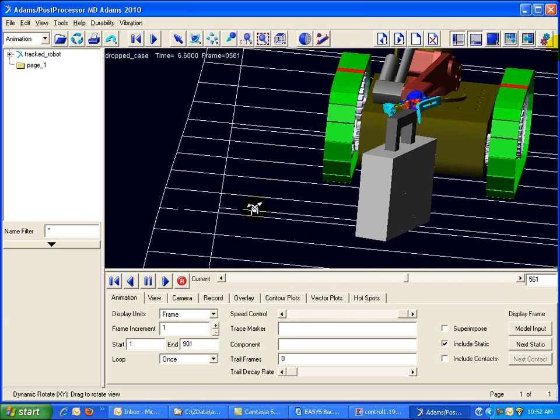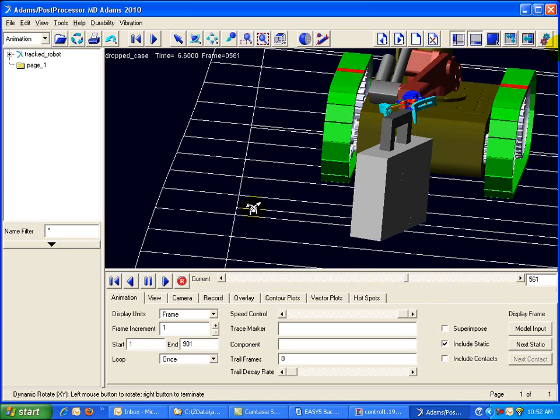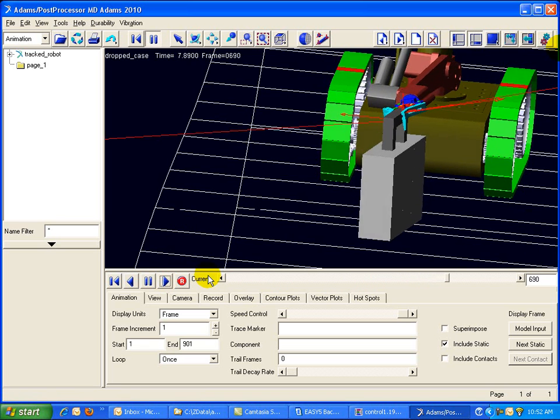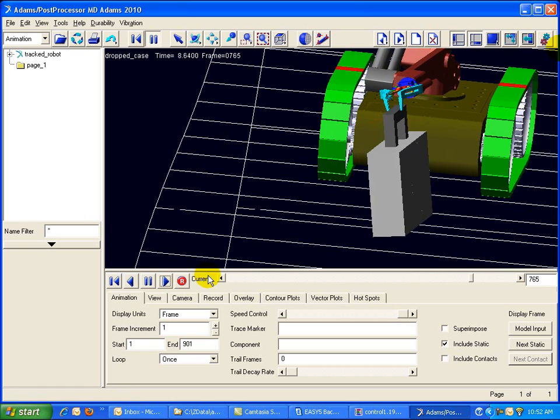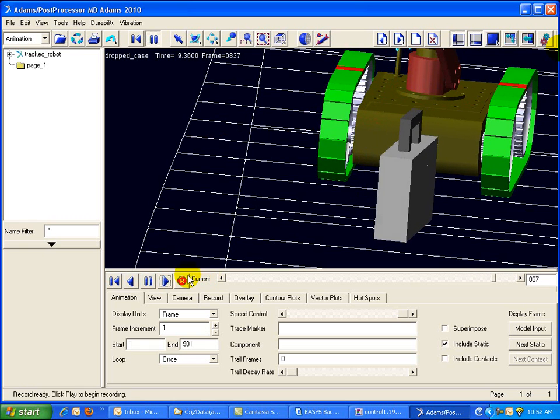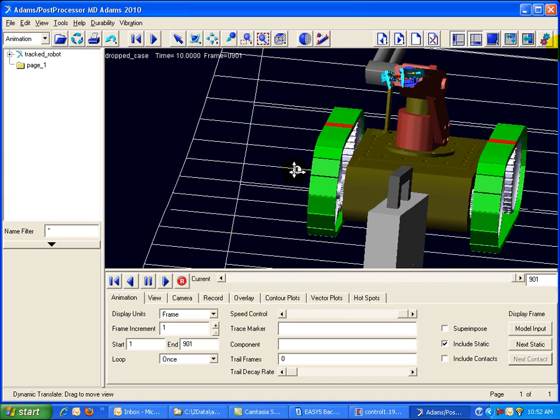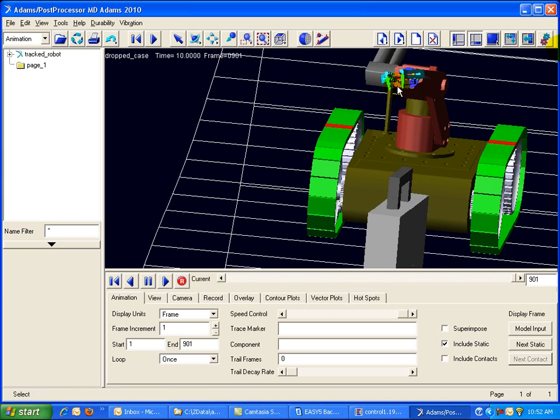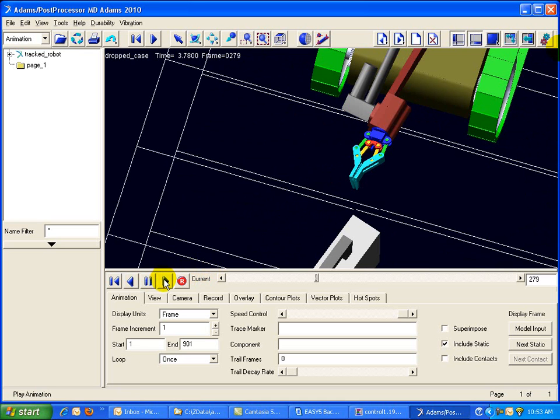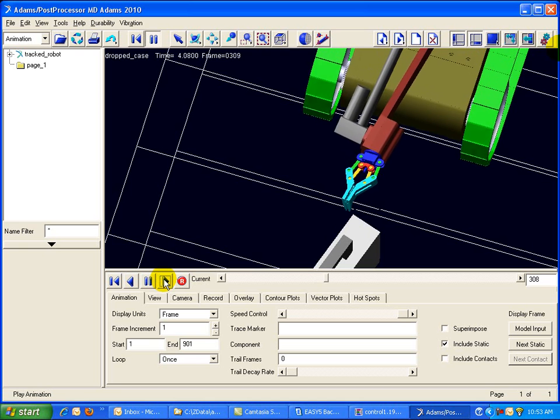So we can zoom in on a different angle and take a closer look to see what happened. You can see the suitcase is at an angle, and the claw is at a slightly different angle. When the claw grabs it, it actually twists the suitcase around so that in effect it becomes a little more narrow. And what happened is the claw wasn't programmed to close far enough. That gap was too wide. We can see this again nicely here.